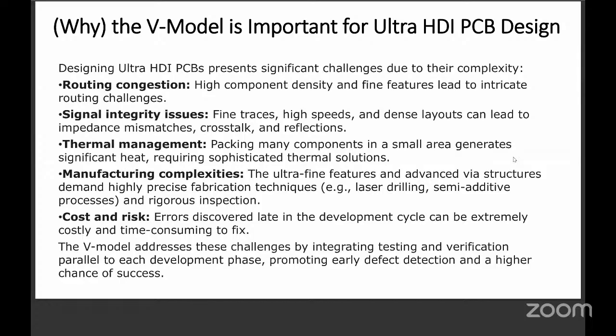Right now, when we are talking of Ultra HDI thermal management, we are still considering insulated metal substrate only. We are not getting into liquid cooling sort of a thing. Liquid cooling comes into the picture. That is the next step actually, that is heterogeneous integration. So right now it is restricted to some sort of IMS sheets only.